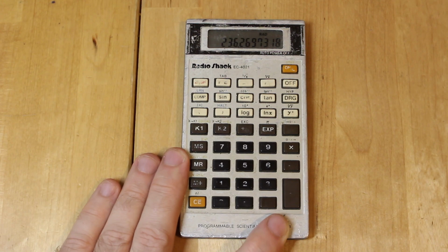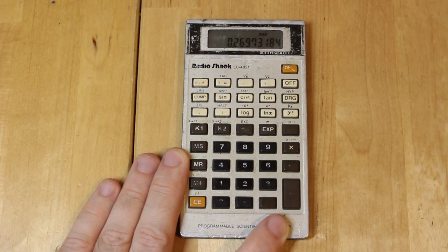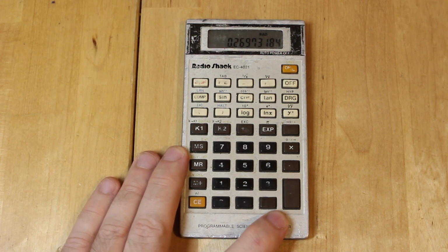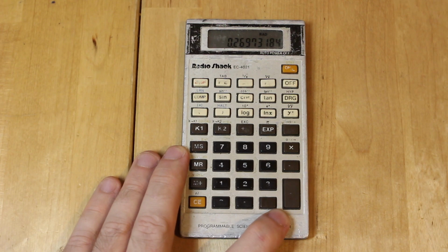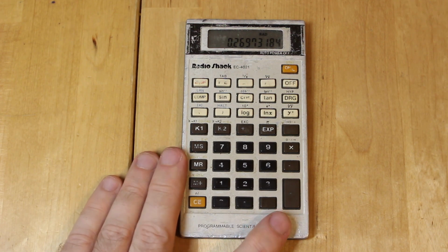So that is a 3-byte approximation to our k value. And if I took that 236 off, there's something left there, but this is just a very, very small remainder from the 4th byte onwards, which we'll just throw away. We're just going to do a 3-byte approximation. So now we have our k value, we can actually code up our Cordic algorithm.